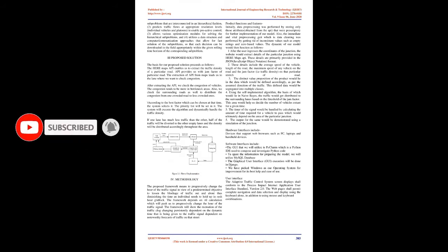Another real-time traffic adaptive signal control system referred to as RHODES was also taken into consideration. The system takes as input detector data for real-time measurement of traffic flow, and optimally controls the flow through the network. The system utilizes a control architecture that, 1. Decomposes the traffic control problem into several sub-problems that are interconnected in a hierarchical fashion. 2. Predicts traffic flows at appropriate resolution levels, individual vehicles and platoons, to enable proactive control. 3. Allows various optimization modules for solving the hierarchical sub-problems, and 4. Utilizes a data structure and computer/communication approaches that allow for fast solution of the sub-problems, so that each decision can be downloaded in the field appropriately within the given rolling time horizon of the corresponding sub-problem.